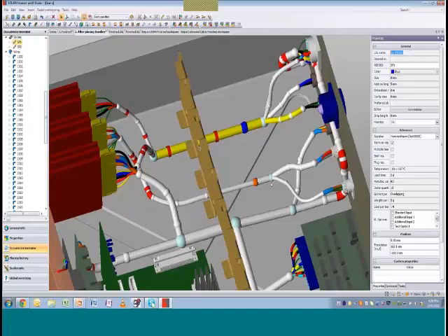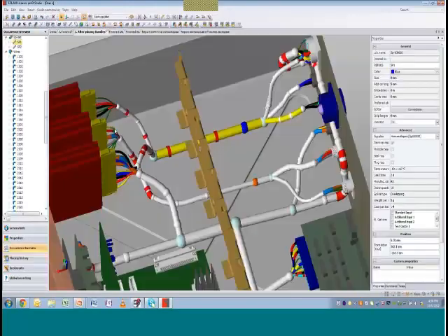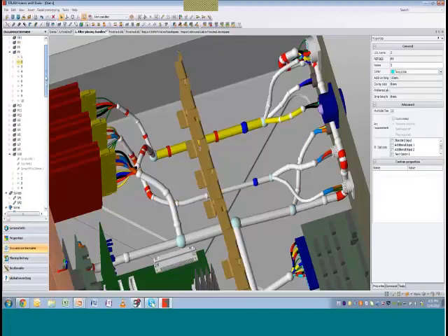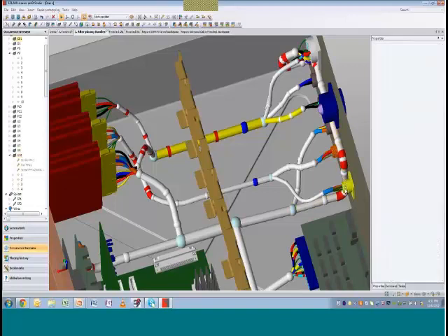So now let's go ahead and go out to the nail board. Now that we have our design all ready to go, we want to go out to our nail board. So here we go to a nail board that has been created for our CA1. Back in our bundle, this harness is indicated as CA1. It's going to this device right here, which is our P9 connector, and it's branching off to two different connectors, the U10 and our CV1.